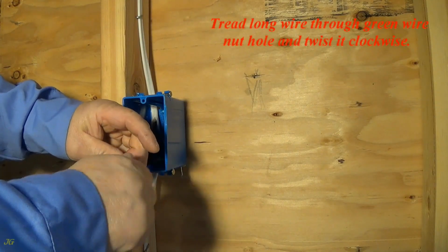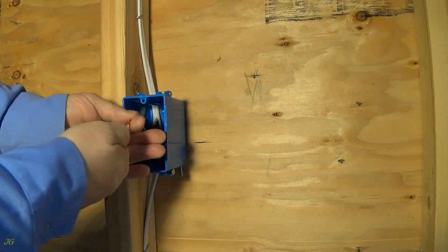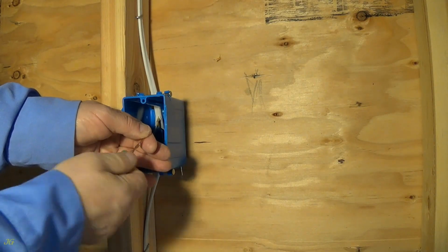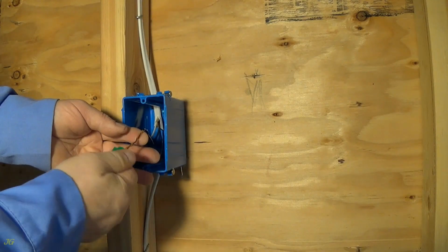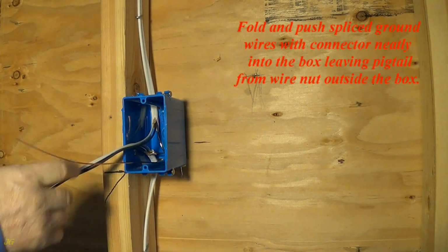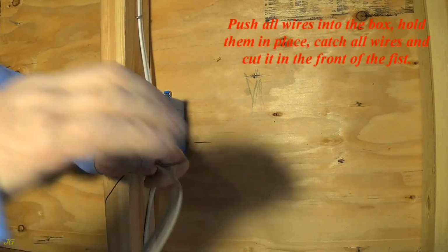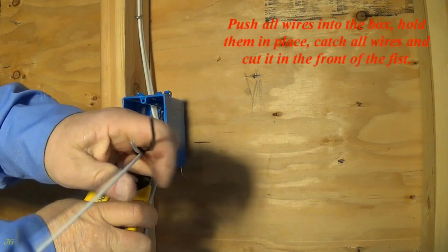Thread long wire through green wire nut hole and twist it clockwise. Fold and push spliced ground wires with connector neatly into the box, leaving pigtail from wire nut outside the box. Push all wires into the box, hold them in place. Catch all wires and cut it in the front of the fist.